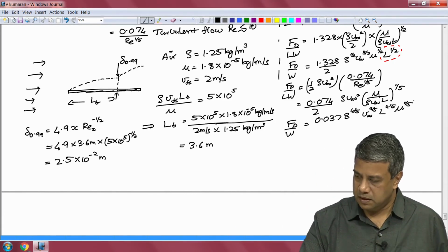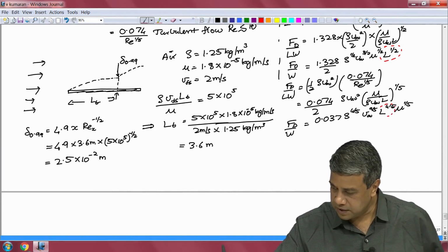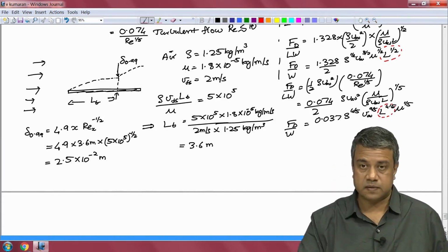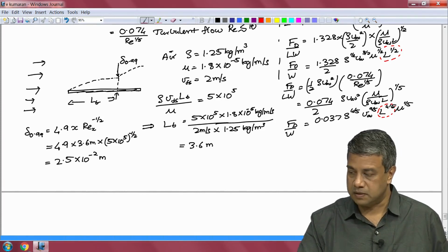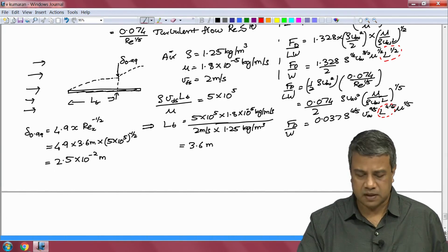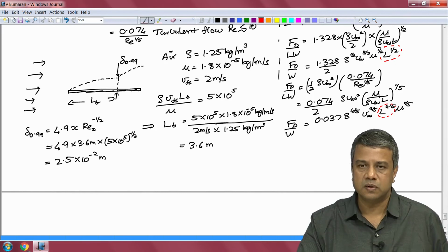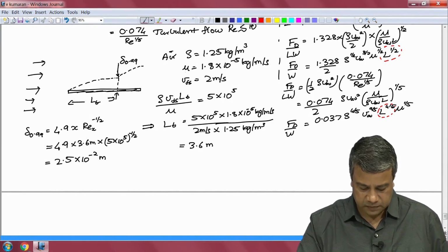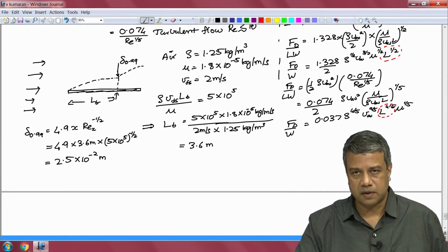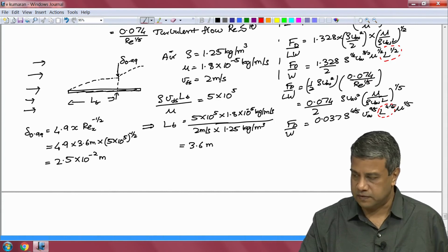And therefore, for a turbulent flow, the total force increases as the length to the 4/5 power, in comparison to the half power for laminar flow. And you can calculate the numerical values of these. It comes to approximately 10 power minus 2 newtons per meter for a laminar flow, and a similar number for turbulent flow, times L power half and L power 4/5 respectively.